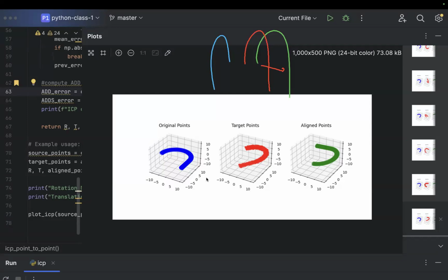This is what a lot of systems out there do. They use a neural network to have a shot at it, because the neural network can figure out where the features are more or less and align it properly, but not very precisely. Then as a second stage, you use ICP to move it precisely into place. Does it make sense?